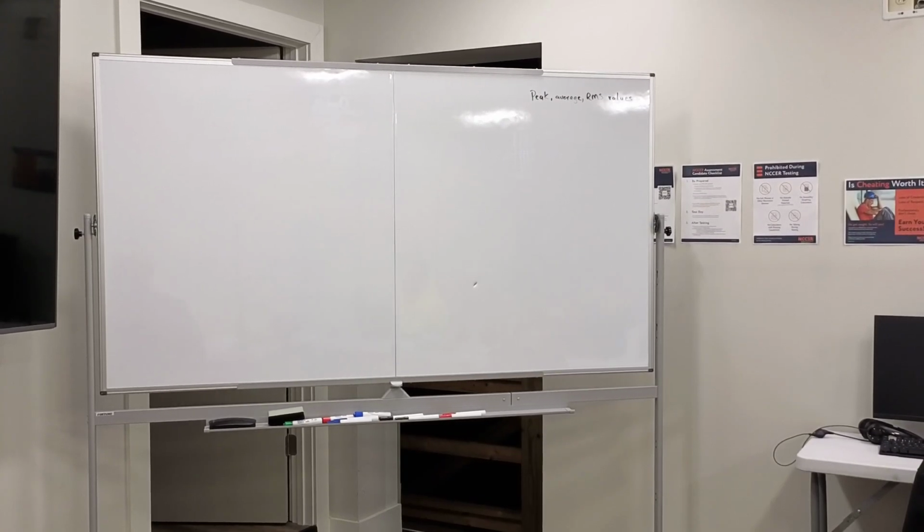At number 2, they have that labeled conductors cutting directly across field, EMF maximum. Does that look right to you? No, because it's at 0. It also says the same thing on 3. It should be EMF minimum. So they got 1 and 2 mixed up. This diagram is just wrong.